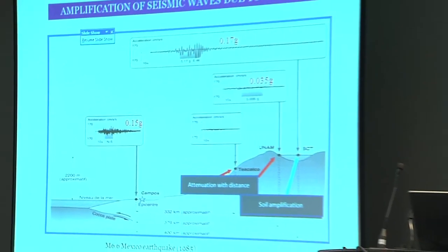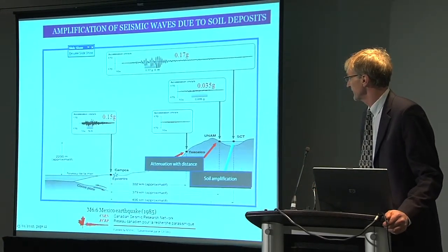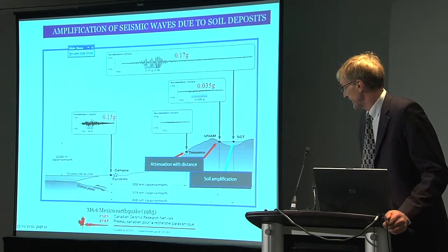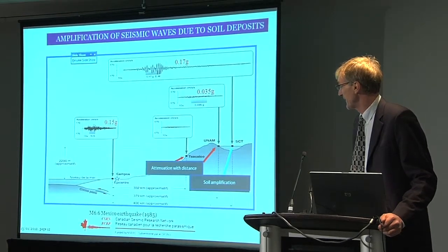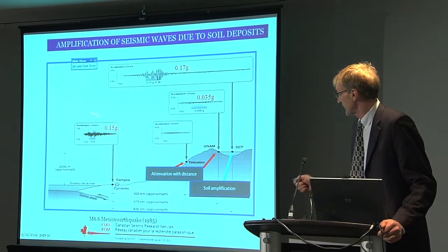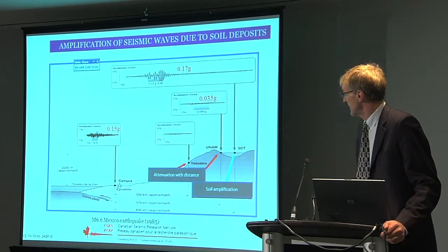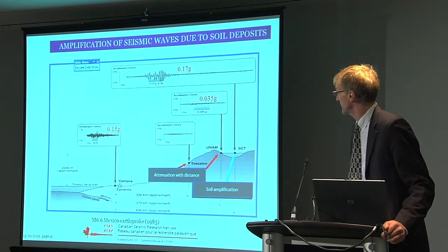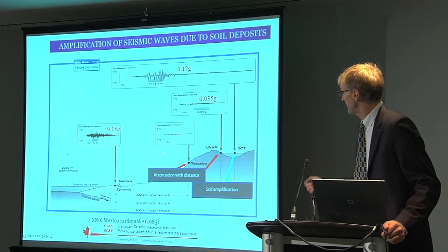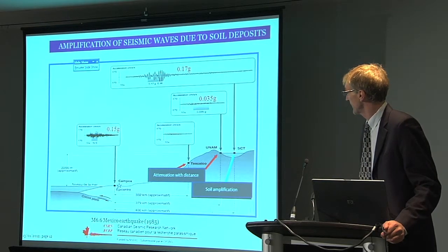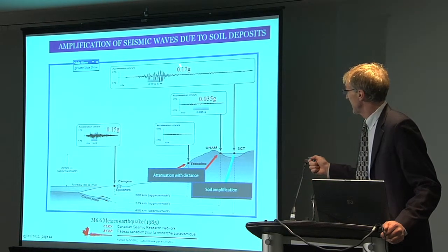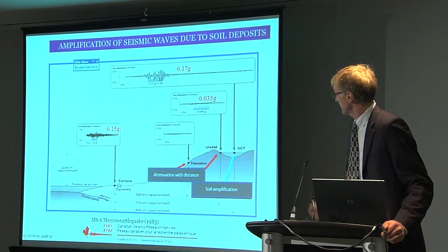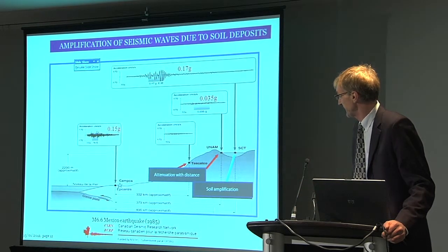Now, in terms of the site effects, Darius has mentioned this earlier. Why we talk about site effects is that this is illustrated by what occurred during the Mexican earthquake of 1985, which was a magnitude 6.6 earthquake. This was a dramatic illustration of what can occur. If we add some instruments close to where the earthquake occurred, the peak ground acceleration that was measured at that site was equal to 0.15 g. As we moved closer to Mexico City, this is the type of thing we'd anticipate, that there is a decrease in the amplitude of the motion and in the peak ground acceleration. But if we go to sites that were in the city over soft sediments, what we observe is that the actual peak ground acceleration observed at the location of the city exceeded what had been measured at close distance to the epicenter.